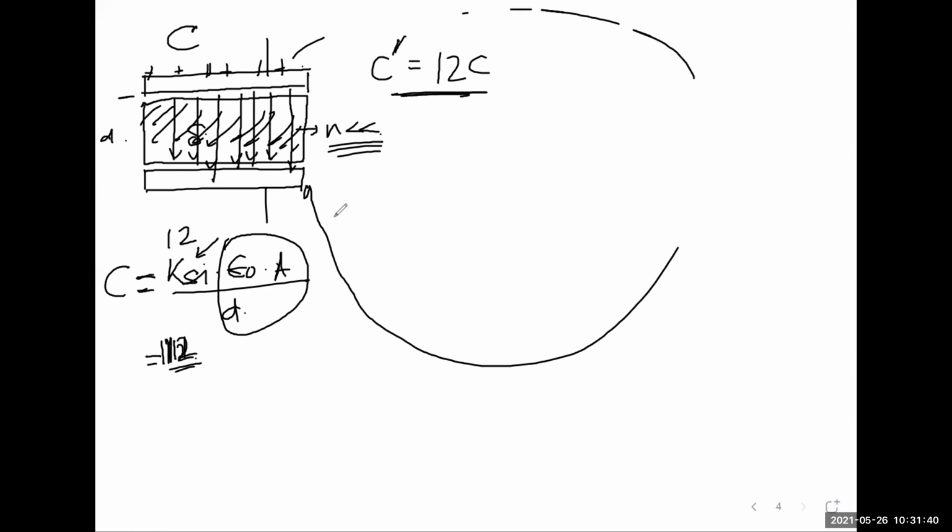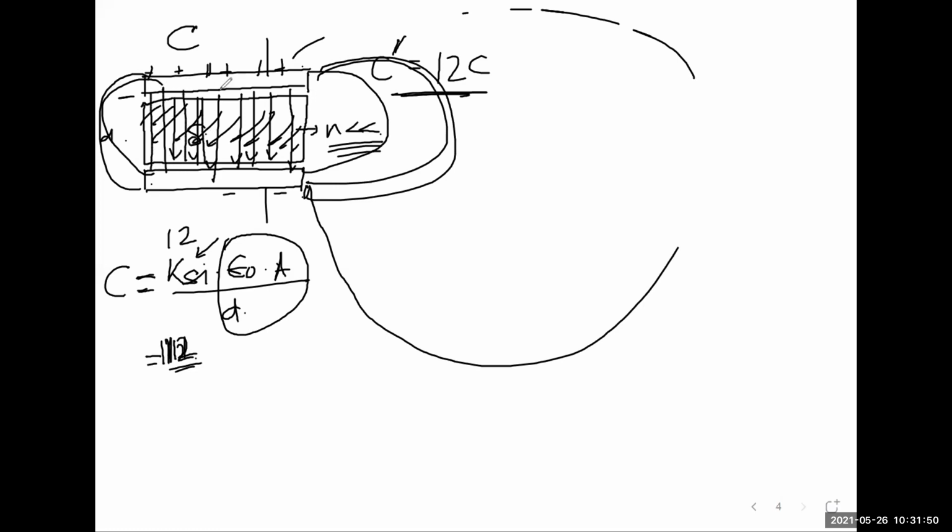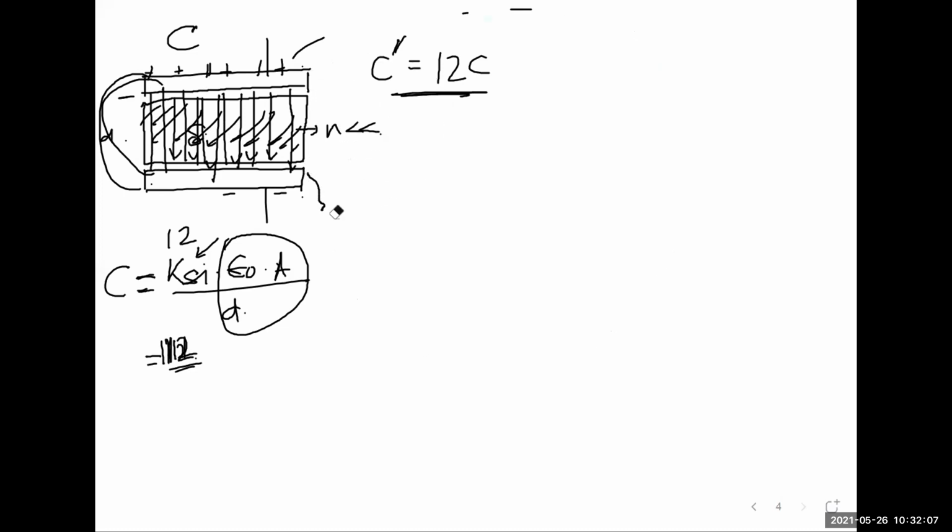So it cannot be 0 because I have negative charges here. Even if there are only fringe fields here, there will be some capacitance, right? You cannot have 0. But actually the field will go straight through the silicon because it is a crystalline material. It's not metal, right? So if it is not metal, then the electric field will go through it. If it was a metal, then the electric field cannot go through it. Okay, so everyone clear about this one?